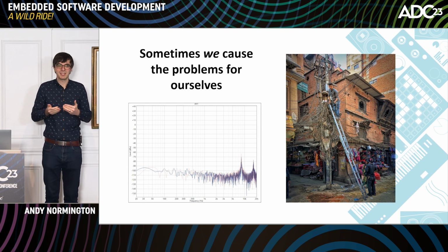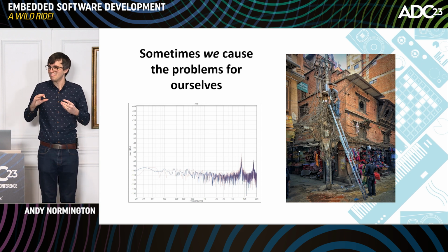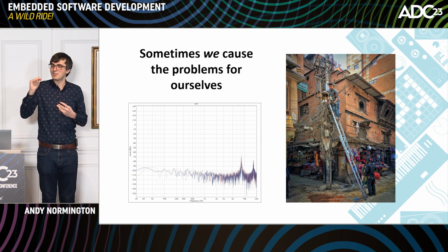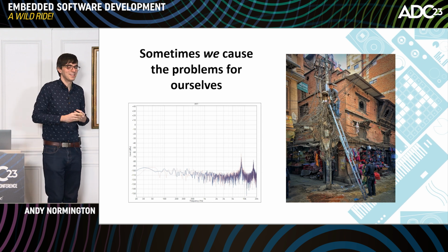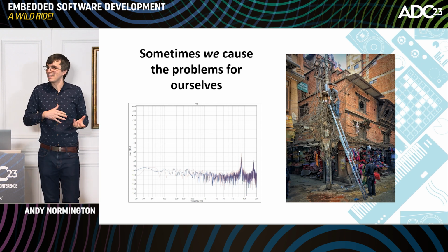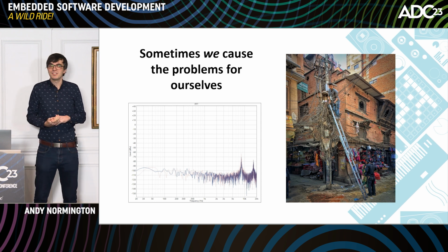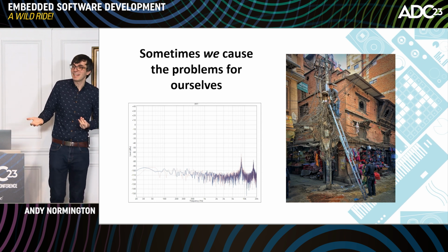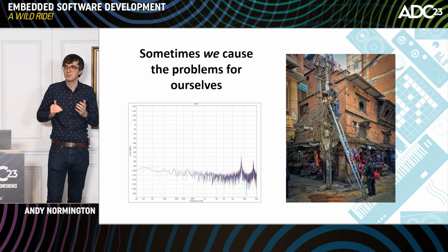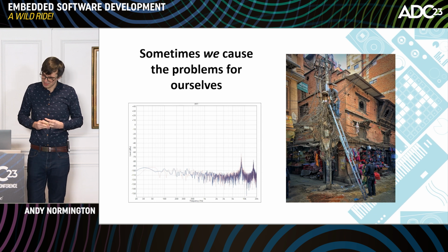Every time we get a USB frame in, chunk of packets, we have to do a load of work, pull a little more current, and that's periodic. So we end up with a periodic voltage fluctuation around the microcontroller in the audio band. So if we're not careful, that can be conducted across to the audio side of the circuit, and we can hear that. And we can do, obviously, electronics mitigations for that, but there's firmware things too we can do. We can batch things up, we can change the order of processing to try and mitigate that.